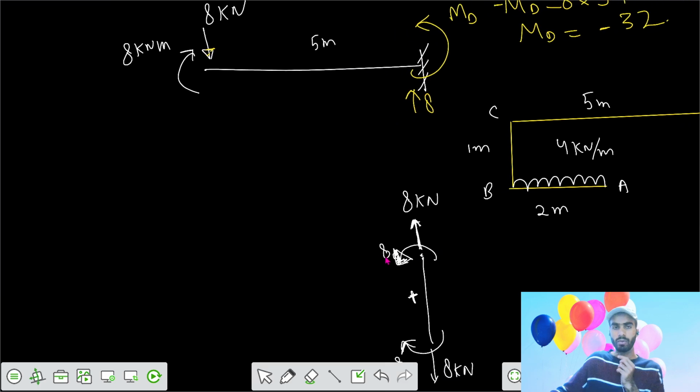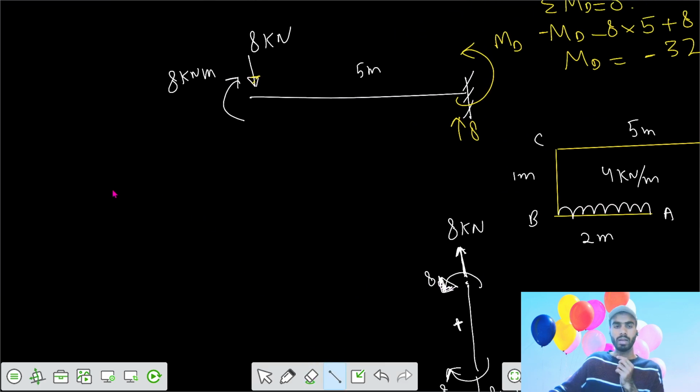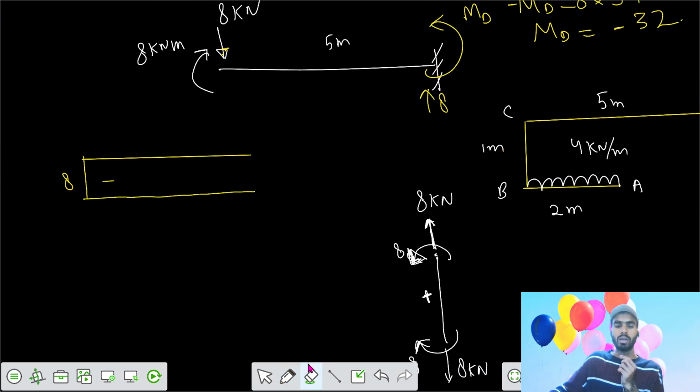Now to make the shear force diagram for this member, you can say this is your shear force diagram. Here it is 8, so we can write the shear force diagram with a downward value of 8 kilonewton. After that, there is no external load, and there is no effect of concentrated moments in your shear force diagram, so it remains constant after the point where the member is joined to your support D. So the value of 8 kilonewton in the SFD.